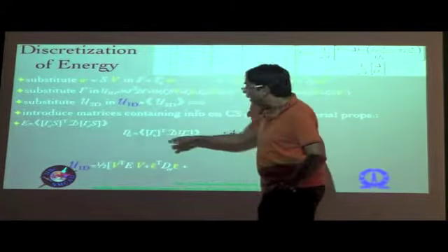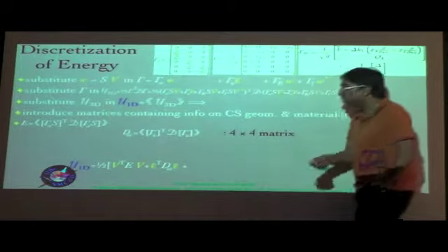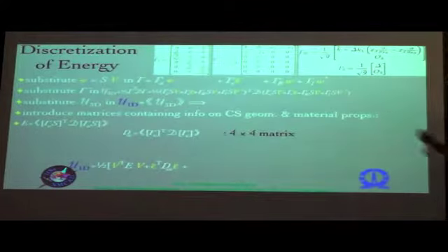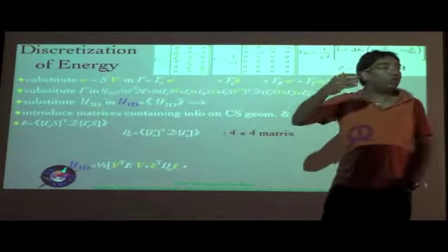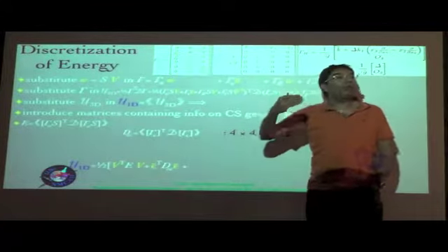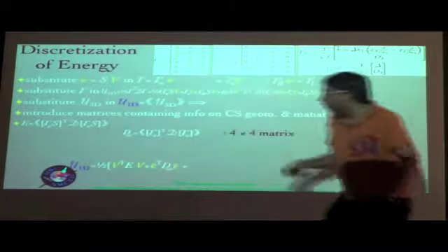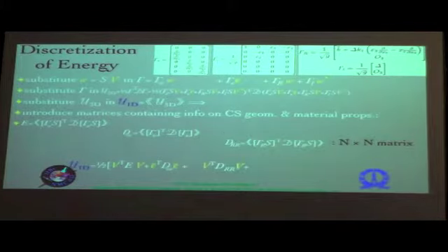So basically you have in this just gamma epsilon transpose D multiplied by gamma epsilon, and that basically contributes to this term, and that is a 4 by 4 matrix because we have just the 4 classical strains associated with it: gamma 1 bar, kappa 1 bar, kappa 2 bar, and kappa 3 bar. And so that is basically what you see over here as well. Contributes another scalar term to the energy per unit length.